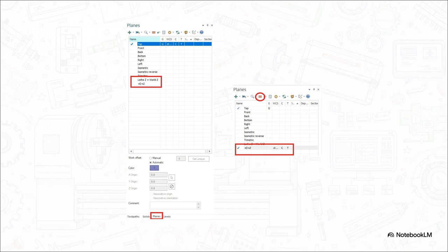Well, think about a physical lathe. The cross slide moves in the X-axis to control your part's diameter. By picking the +D +Z plane, we're basically telling Mastercam that our vertical drawing axis, the D+, represents the diameter, which is that physical X-axis on the machine. Trust me, setting this up now makes plotting your coordinates way more intuitive later.